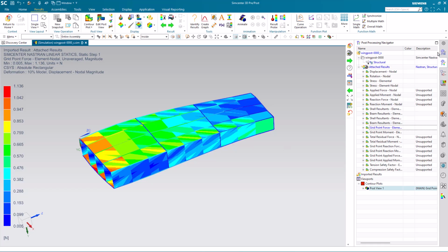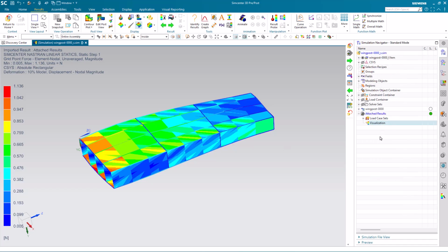And that's how you post-process results files with no geometry in Simcenter 3D as of version 24.12. This is limited to linear statics solutions and multi-step nonlinear 401 solutions in 24.12 and 25.06. And I believe that will be the case also for 25.12.